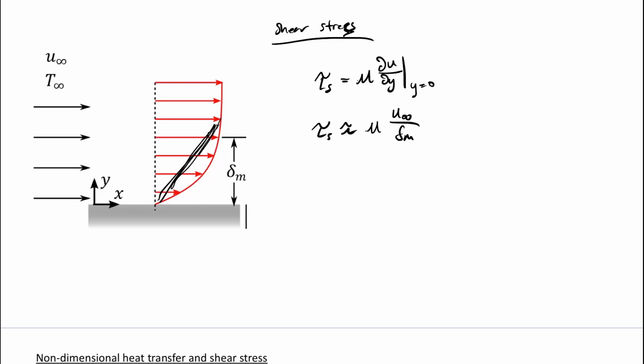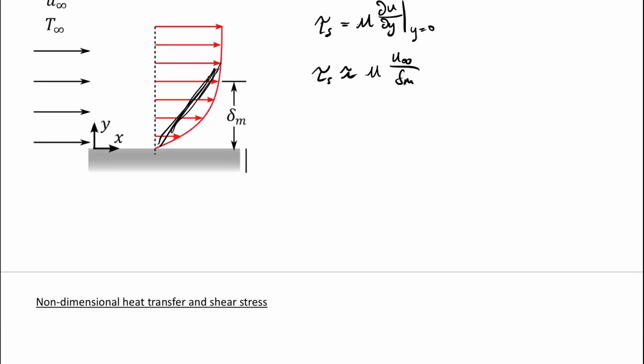One thing you run into, and why it's important to think about the shear stress: if I want a higher heat transfer coefficient, what's one thing I can do? I can break up the boundary layer. If I break up the boundary layer, my delta is going to be smaller, momentum and thermal. But what happens to the shear stress if I have a very small delta? It's going to go up. So there's this constant tug of war in heat exchanger design between low delta P, pressure drop across the heat exchanger, and good heat transfer. You're always fighting this battle, no matter what you do. It's a fundamental characteristic of the system. That was really the only point for this slide.